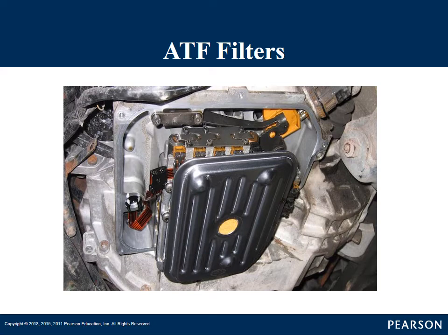There are some transmissions, and more transmissions are like that, where there's not a replaceable filter. There's not a pan to remove and replace the filter. If there's a filter element in there, the only way to replace it is actually to take the transmission apart. That is becoming more and more common. The idea is that they think that they're running cleaner and cleaner. The units are sealed up tighter, especially as we're seeing less and less dipstick tubes on transmissions. So we don't need a filter to change.